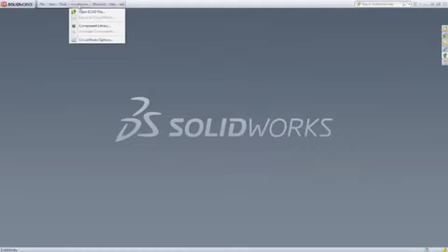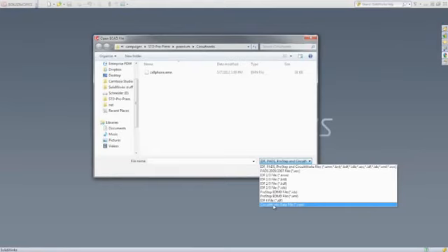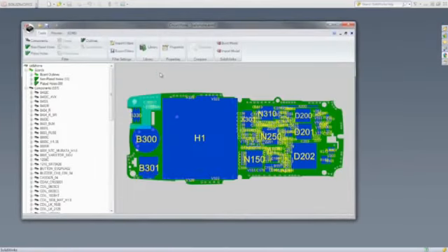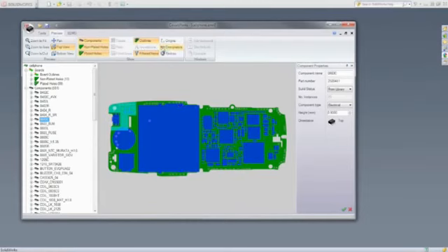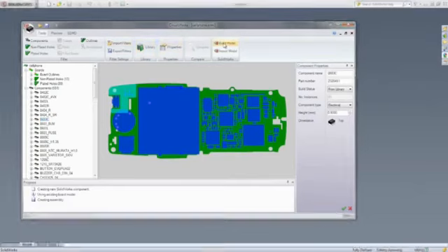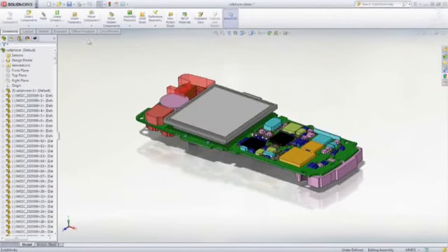SolidWorks Premium provides tools that make it easy to work with PC board and 3D scan data. CircuitWorks is a bidirectional electronic CAD translator for creating 3D models of circuit boards in SolidWorks. The dedicated CircuitWorks interface lets you open, compare, and save ECAD files with support for industry standards IDF, PADS, and ProStep EDMD. You can visually inspect the board, modify ECAD properties, or use the powerful filters to reduce complex features that are not required in SolidWorks.